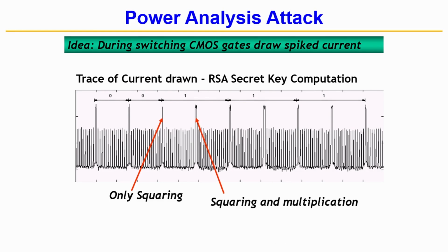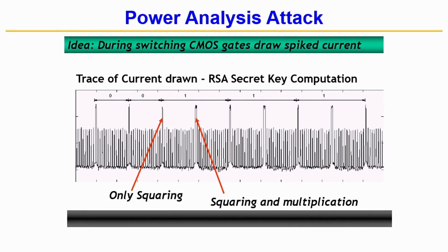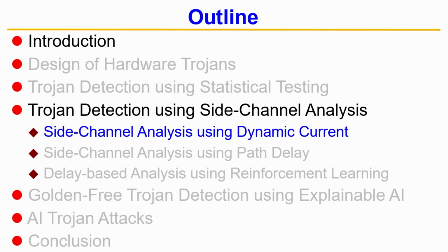So, you can analyze this simple thing, and when this idea first came in, the first attack basically broke the security of smart cards. Of course, this is a simple power attack. These days attackers are also smart enough; they do not want to keep this footprint, they will either make this one bigger or that one smaller, but whatever it is, you can do differential power attack and many sophisticated techniques. This is power based side channel attack, power or dynamic current based.